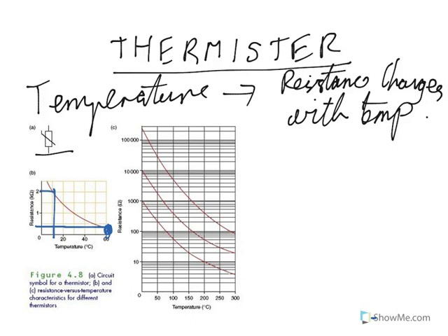Now the one on the right there, option C, you'll notice there's 3 lines. So what that is, is data for 3 different thermistors. You'd have to be told which it is. You'll notice that the graph paper there is a bit different as well, and this is because it's log graph paper.